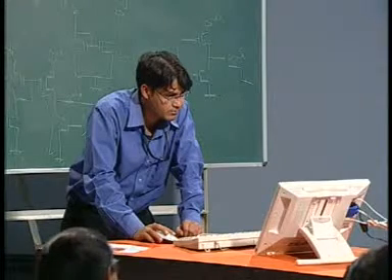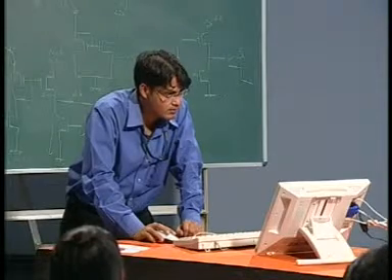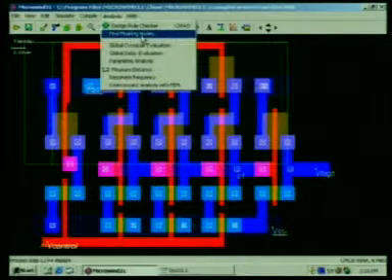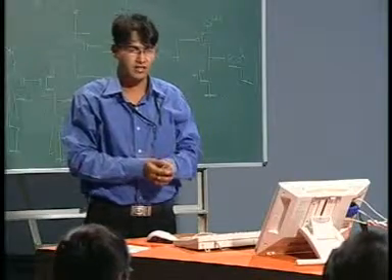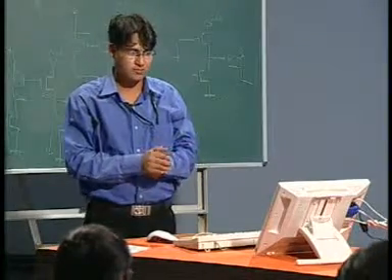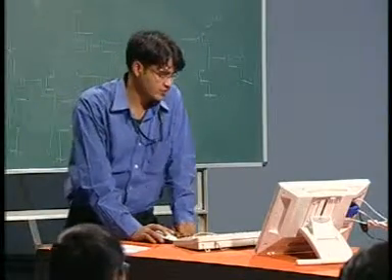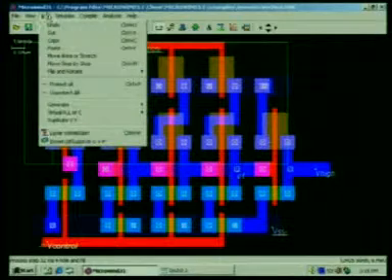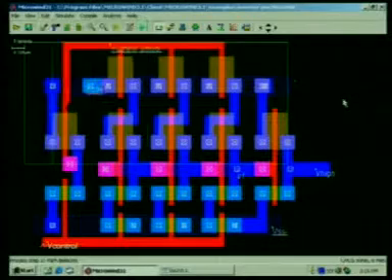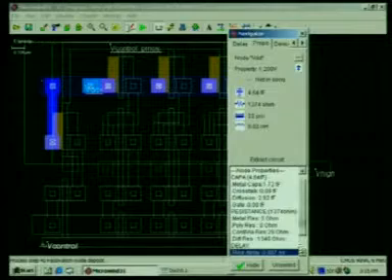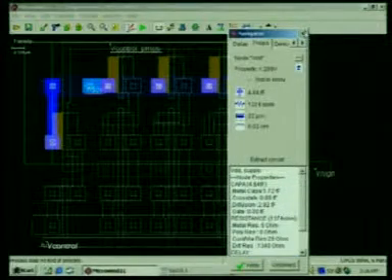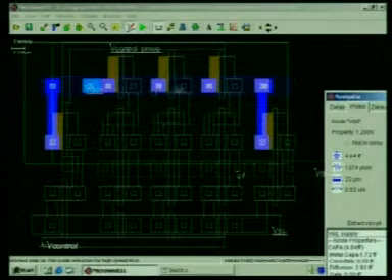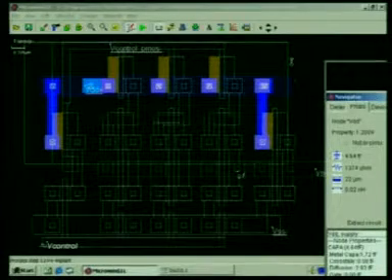Suppose I take this one. With these analyses you can find the floating nodes, because this is a big design, so there is a possibility of some errors. It will analyze the floating nodes, because they will create a great problem for you. You also have to analyze resonant frequency, this kind of thing. There is a navigator window; just double click this. See, all the data will be provided here: resistance, diffusion, delays, capacitance values, VDD. You can also check the interconnects; for this layer, these are the different interconnects, and these layers are connected.